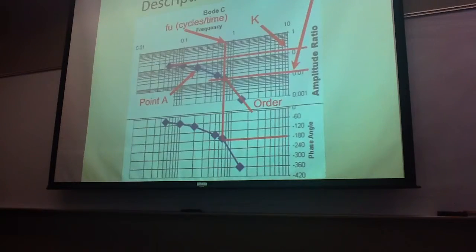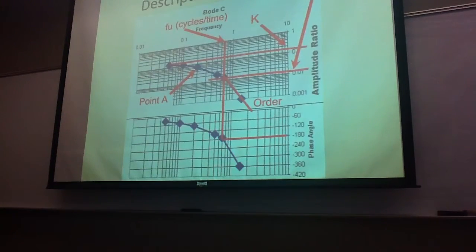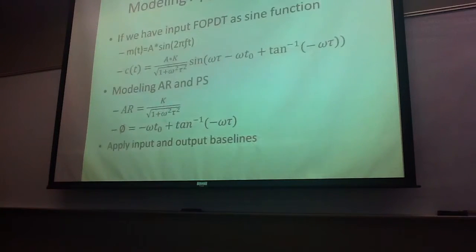Then with all that, we can actually graph all of our frequencies at different times. We actually graphed about 10, halving the frequency and doubling the frequency every time. The things that we can get from this would be the gain, the KCU, the order, and the ultimate frequency, as was talked about earlier, so I won't bore you to death. The gain is at the asymptotic value, and at negative 180 degrees we can find the ultimate frequency, which helps us find the controller gain.